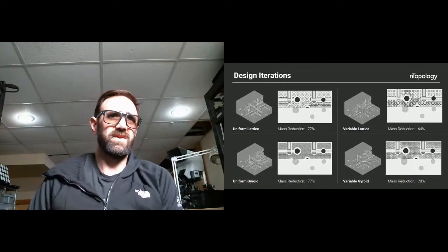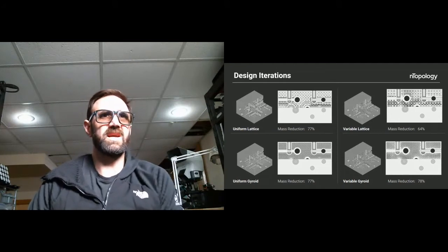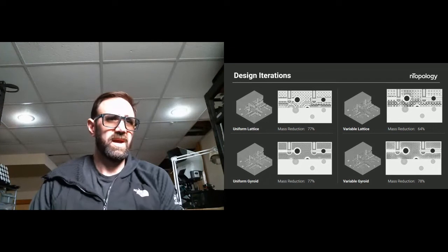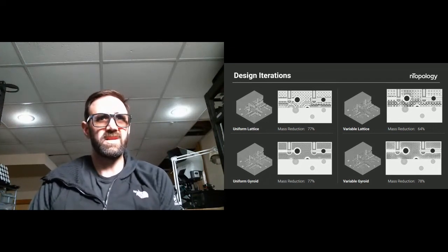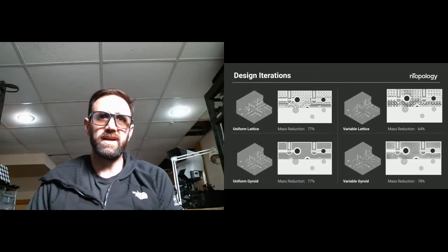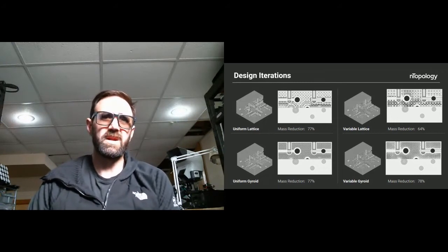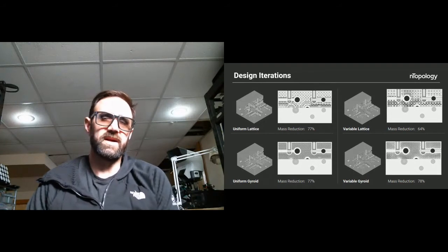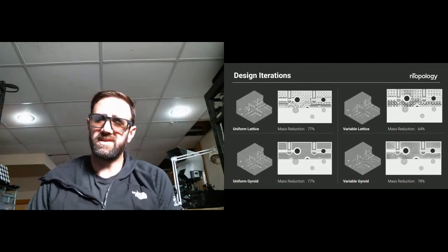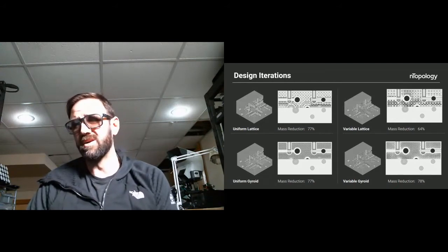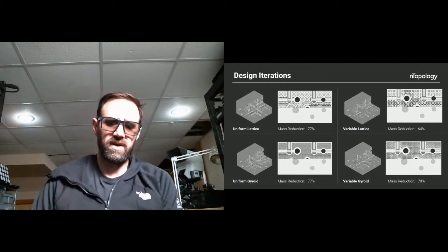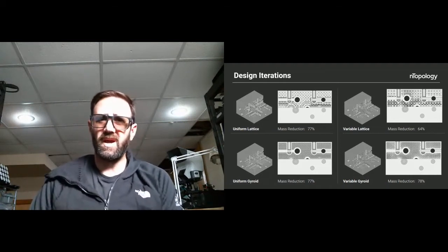Along those lines, for this manifold, we also took a topology optimization approach. This is another technique to remove material where it's not needed. In this scenario, we designed for an additive printing setup. So we minimized material, specifically unsupported material, and basically only thickened the walls where we needed them and preserved the outer interfaces where you would have hoses or other clamps mount to the manifold.